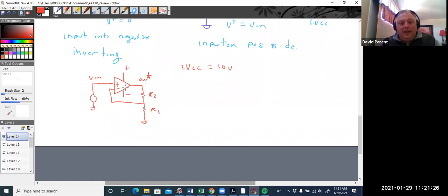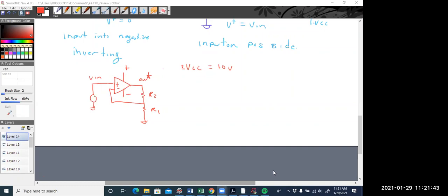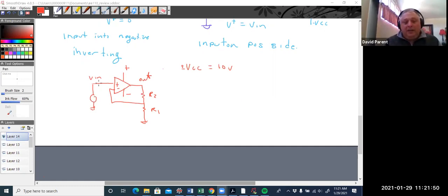Okay. Now I'm sorry, I heard a few answers, but I didn't quite hear the answers. Is this an inverting or non-inverting circuit, the red circuit? Anyone? Would it be non-inverting? Non-inverting, yeah. Okay, all right, people are putting that. So yeah, V in comes in here, and there's a feedback loop to the negative side. I've just drawn it differently.